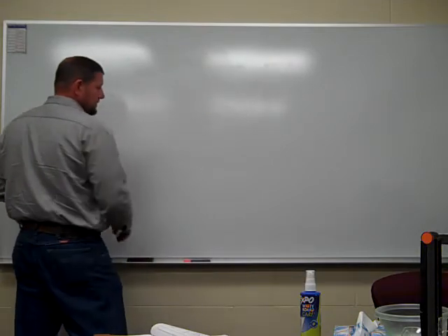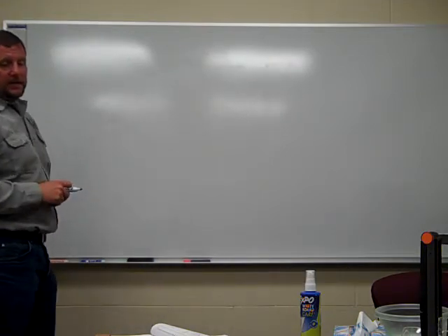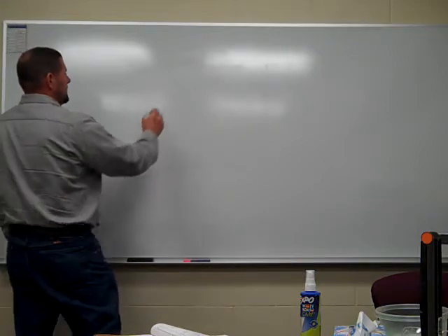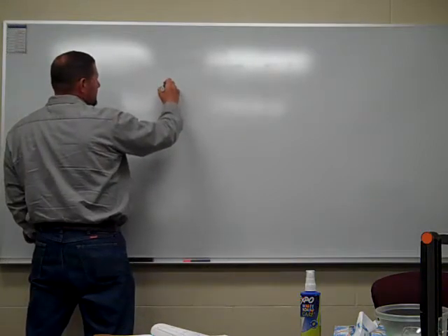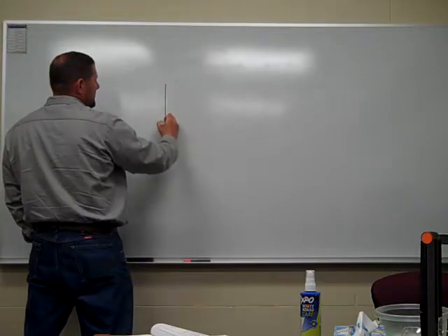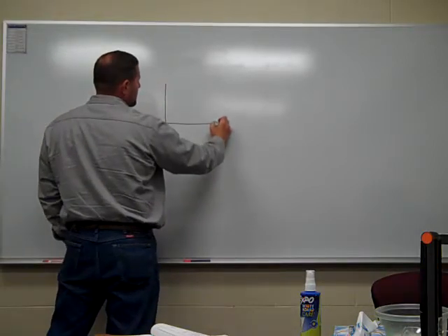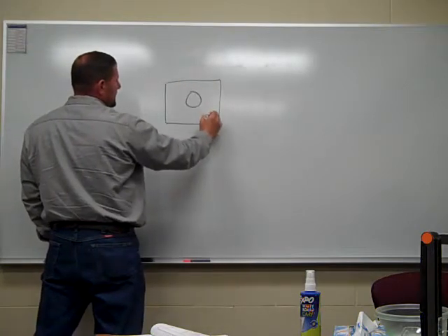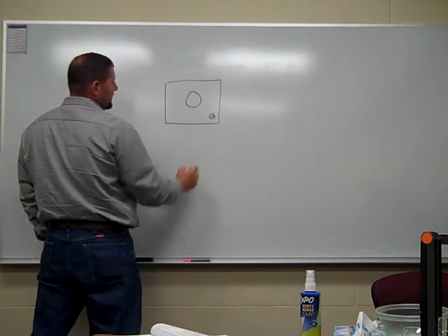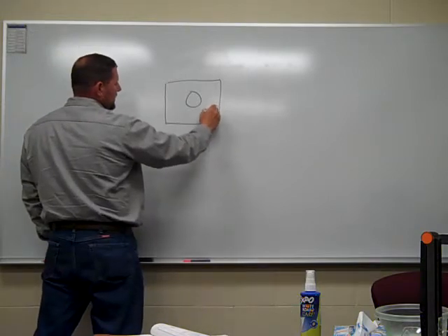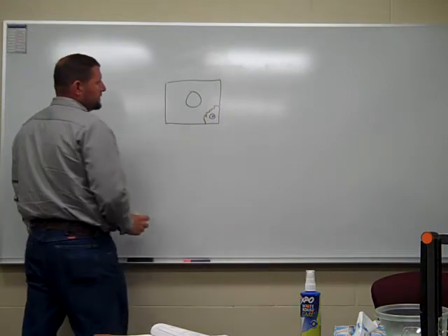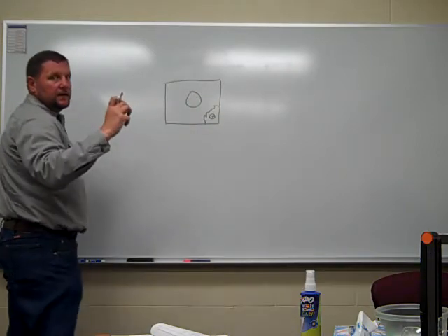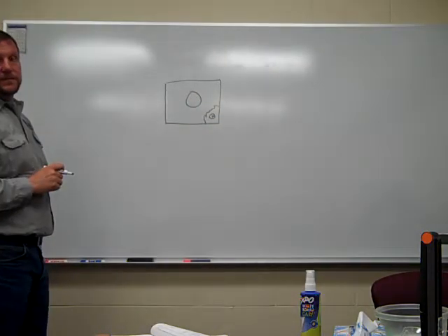Short break lines, they're kind of like a cutting plane line. For example, let's say we have this object, there's a circle, there's a hole and a countersink hole. There might be a little break line. They're usually jagged. So what they're doing is taking that little jagged part out so you can see inside.